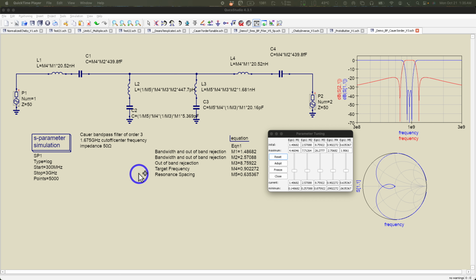In this part of the video, I'm demonstrating a Cauer filter that was created using the tools within QucsStudio. And that's Cauer filters done with these third order and with this frequency. And so what that does was create a prototype that I can then go in and add multiplier values that just scale everything. So if you want to move the whole response within frequency, just multiply all the components by a variable. But then when you want to try and move the spread of the resonances or other parameters, you rearrange multipliers for the other components that are in balance.